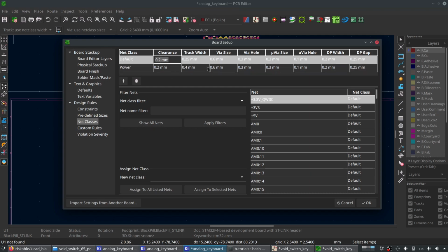In theory, you might want to use a little bit thicker trace for your analog traces, because then you will get a little bit less signal loss. But from a keyboard perspective, it's not going to matter that much. There's also a trade-off where if you make it a little bit thicker, it just means there's that much more surface area to act as an antenna, right? And we don't want that. We don't want our traces to ever act as an antenna.